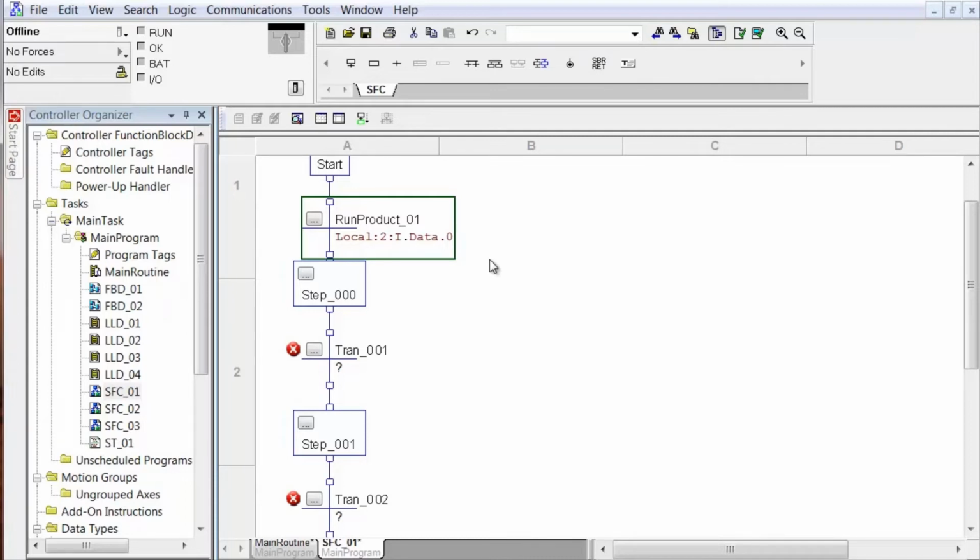We're going to do enough of editing with sequential function charts, especially procedures you haven't seen before. But eventually we'll thin it out. It's assumed that you've already caught on. You could have pressed enter or just click. The focus is still there. So now we want to name steps 0 and step 2.